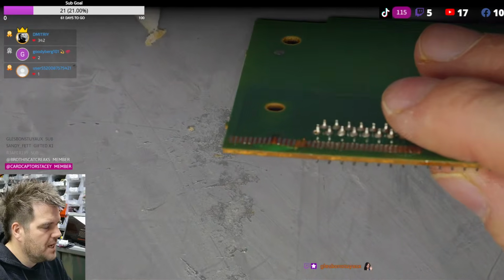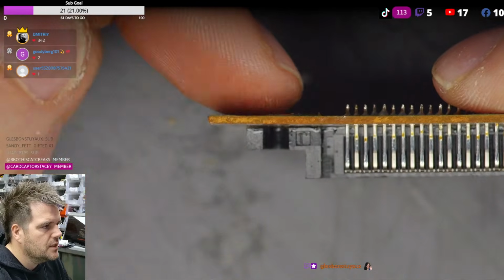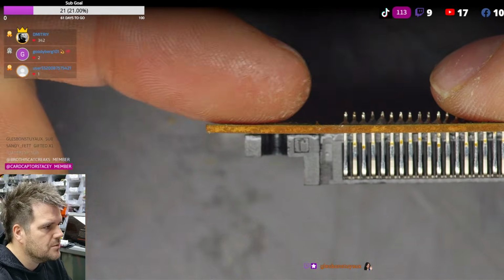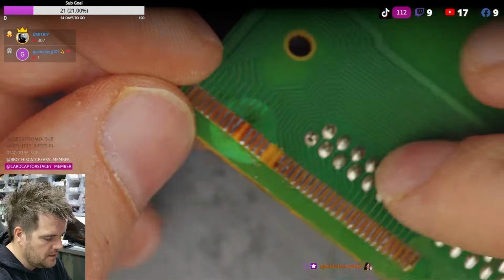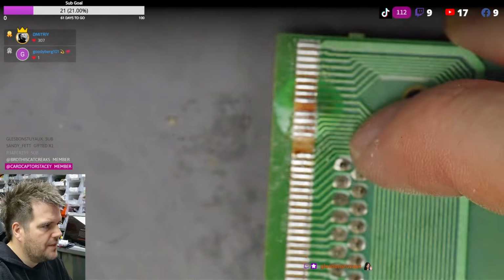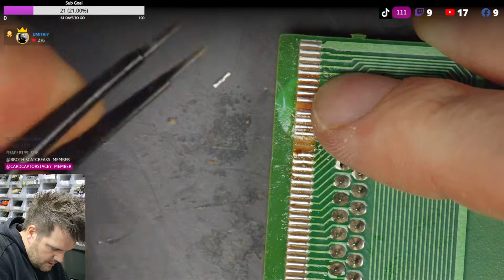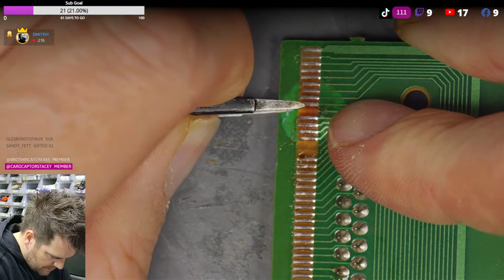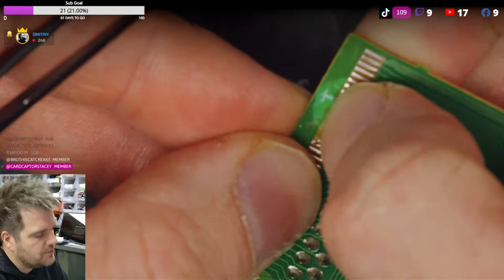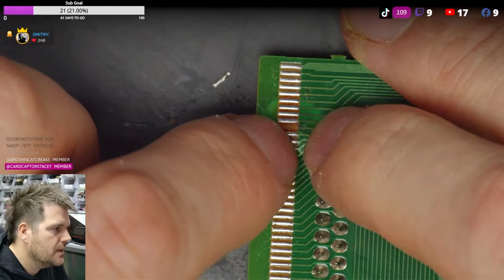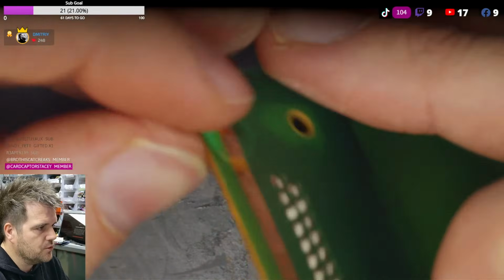And this is also a paper board, so you can't really see much and it's not going to damage much, but there's a little bit of a hump there now, very small. So you can just about see, if I put my finger there, there's like a little bit of a hump there. You can normally pierce and flatten these down to get it sitting flat again. If this happens, it looks a bit brutal, but you can stab through the board to get between the layers and then push effectively the air out, if you will. That's what popcorning is, when it's normally from too much heat or moisture in the board.